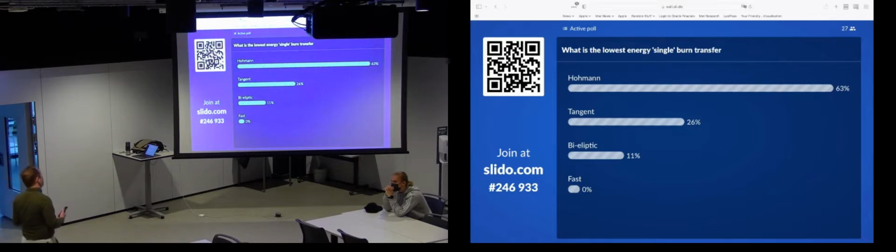And depending what you have on board or what you're trying to do, you may not have that time. You may want to get there much faster. Maybe you want to observe something. Or maybe you have a payload that might expire after a period of time. You have so much liquid helium on board for your telescope or the like. Now, when we're doing departures out into the far solar system, we'll do gravity assist flybys, all of that stuff. They can bring our rocket energy down even more, but we're using the gravity of the planets around us to extract energy. But for simple transfers from A to B, the Hohmann for a single burn is our lowest energy one.